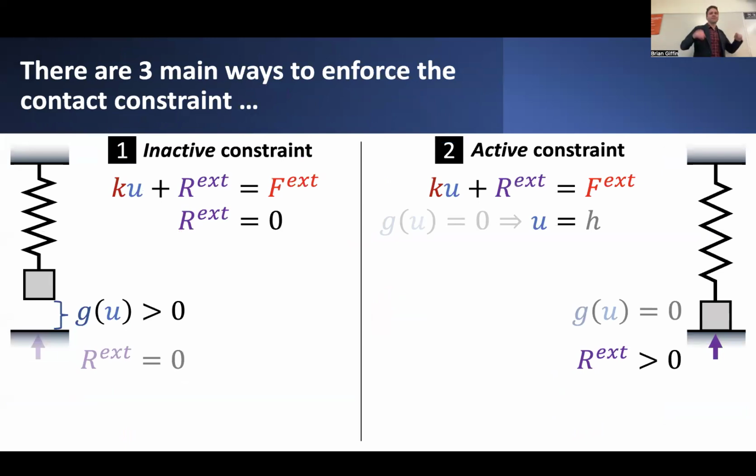I want to enforce a few conditions on how exactly we solve these problems in general. Supposing I wanted to go about actually solving this kind of problem as we posed it, how do I use all of those equations that I just proposed? The equilibrium condition is certainly the one that we want to solve most of the time when we're solving mechanics problems. But once we introduce this additional variable for the reaction force, it is, in addition to the displacements, a new variable we have to solve for and set up a system of equations to solve for it.